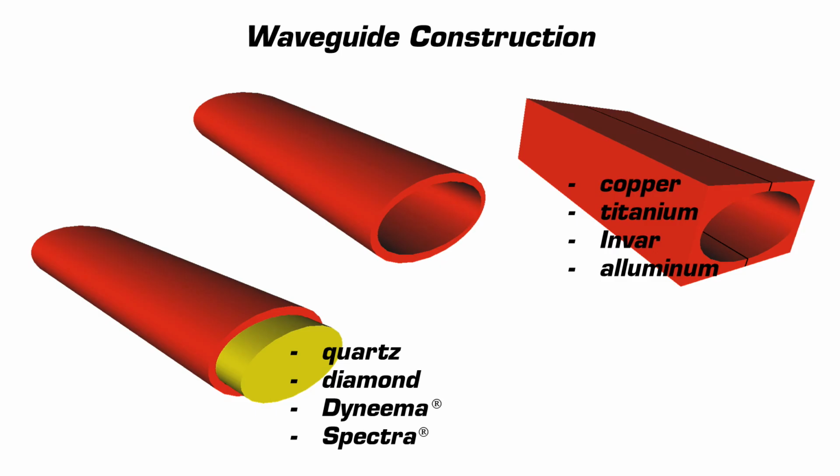Nowadays, additive manufacturing or 3D printing offers highly flexible design and manufacturing options. However, every manufacturing process is completed with some form of electroplating, sputtering, adhesive bonding, or injection overmolding in order to apply a low-loss metal coating to the waveguide. Depending on the required mechanical robustness, accuracy, and RF performance of the waveguide, a specific manufacturing process is chosen.